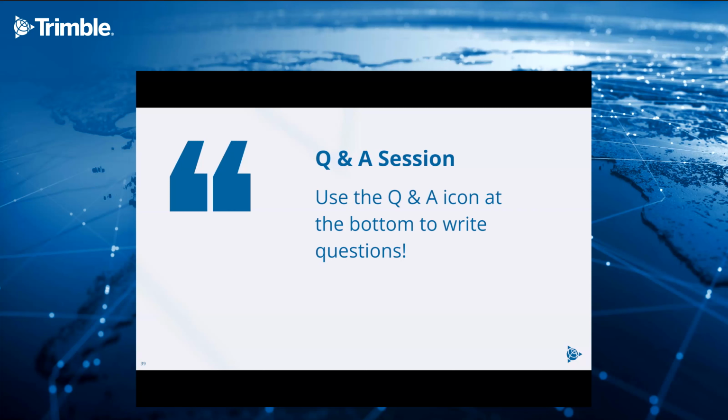And we support various datum definitions like the ITRF 2014, ITRF 2000. We support the American datum, the European ones, etc. So at the end, when you export your solution, that's important what you click on, what you activate there, and then you will get what you need.